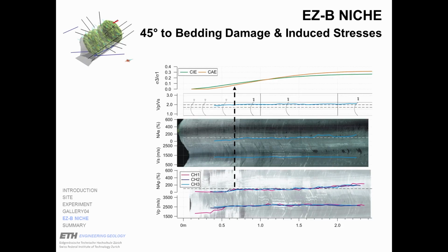So here we now compare the simulated stresses from this model, and what is shown here is only the ratio of sigma 3 to sigma 1, which is called the spalling limit, which has been identified as an important property for excavation-induced fracturing, or spalling, in granite. What you can see on the other parts of this figure are the optical images.